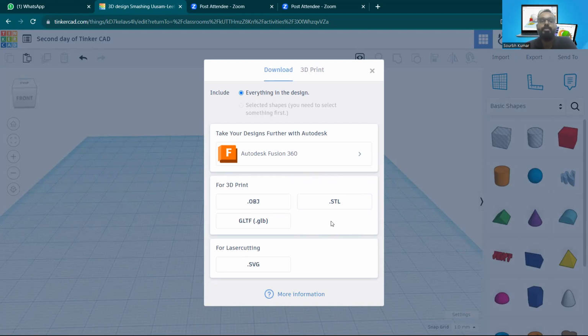And apart from 3D printing, like the way we are depositing the material one layer at a time, we can also go for laser cutting. Suppose you have to build the outer frame for the drone itself, then you can go for the SVG file, and it can be utilized for various CNC laser engraver machines, so that you can cut out the portion in wood sections and the thinner sections of metal, not the thicker sections.